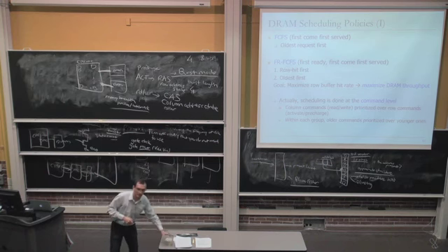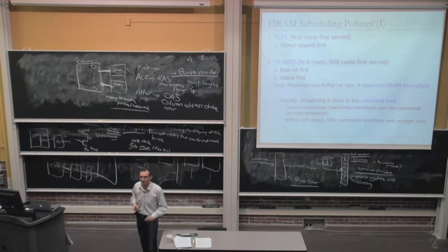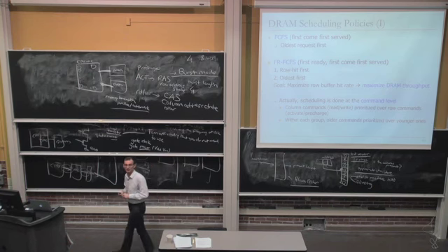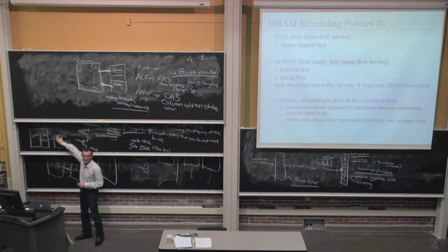Yes? Now, if you're putting this memory controller on chip, on your CPU, with the interface to the DIMM, then aren't you really coupling it with the protocol of the DIMM, because it's there at the command level? That's right. Exactly. Yeah, you are coupling. So this protocol now has to be the protocol specified by the DIMM.